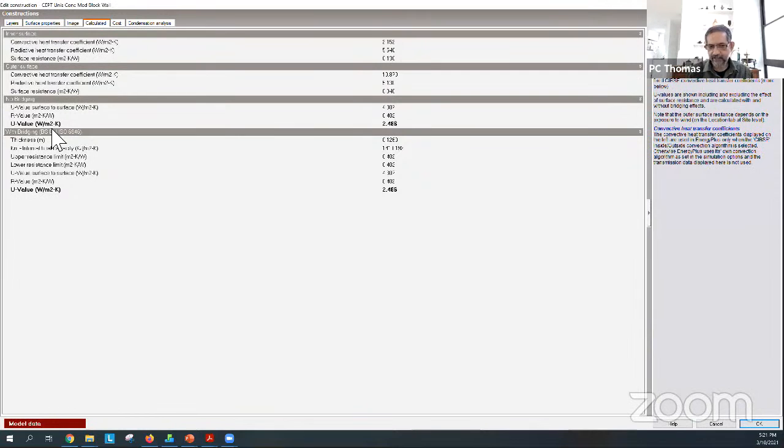an insulation layer, then if there was a material that penetrated through that insulation layer, so it connected the outside and the inside of that insulation layer, then it derates the performance of the insulation because you have a highly conductive penetration from one side to the other between and through that insulation layer. So you want to account for that derating, and if you do, then the bridging comes into effect.